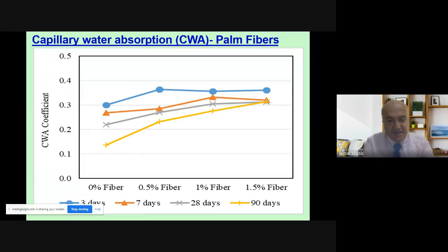It's a simple test we do, and my earlier paper got many citations. That was back in the mid-90s. Sometimes you can relate it to SEM results, to MIP results, that's mercury intrusion porosimetry, and so on. So it's a simple test, but yet it's effective.